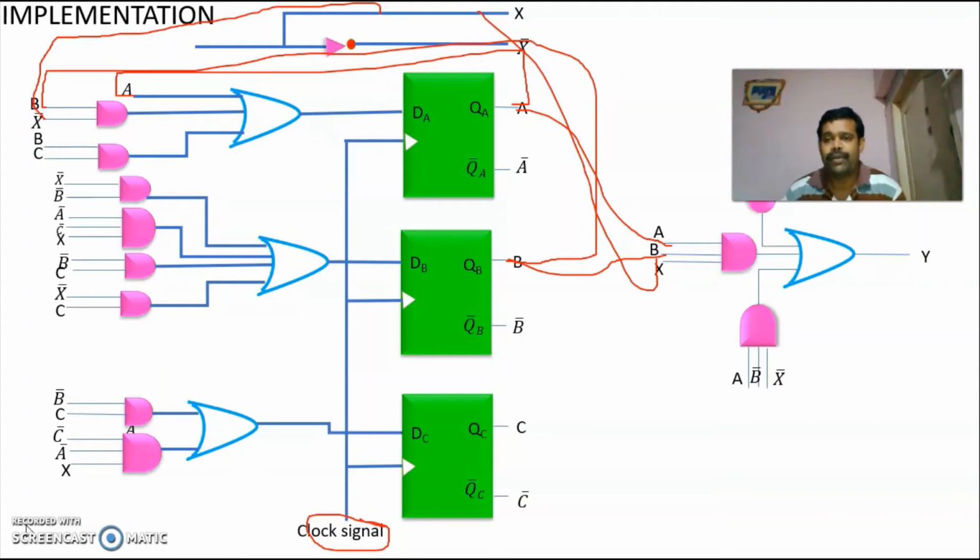We have used 3 bits to represent each state. So we have used 0, 0, 1 for A and 0, 1, 0 for B, and so on. After that, we have converted the state table into a transition table. A transition table is nothing but a table that consists of binary values instead of the alphabets A, B, and C.